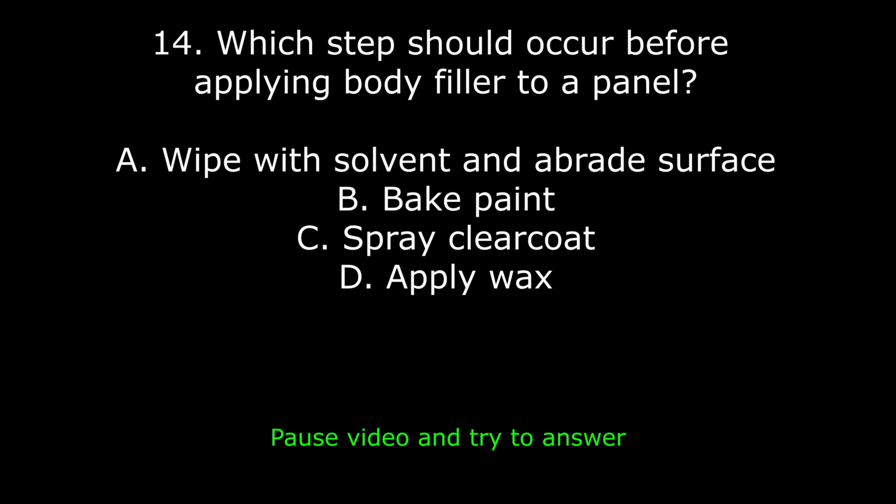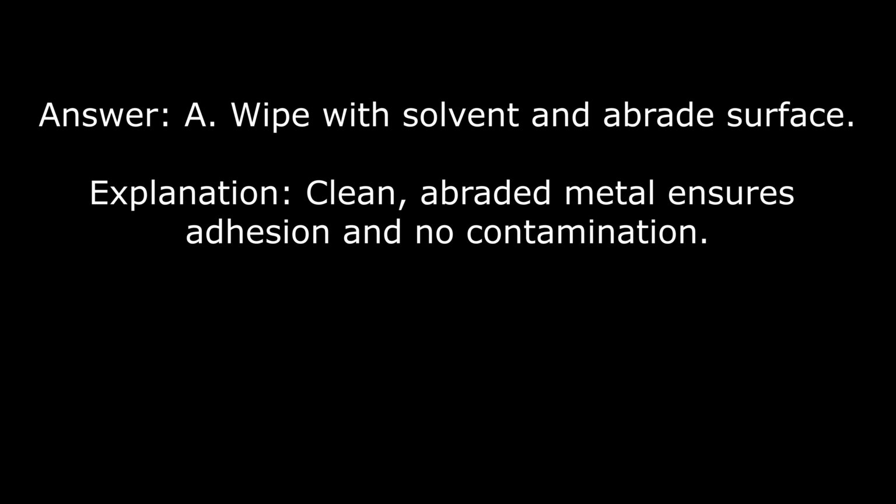14. Which step should occur before applying body filler to a panel? A. Wipe with solvent and abrade surface. B. Bake paint. C. Spray clear coat. D. Apply wax. Answer: A. Wipe with solvent and abrade surface. Explanation: clean abraded metal ensures adhesion and no contamination.